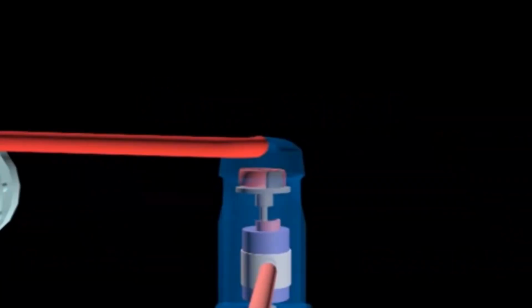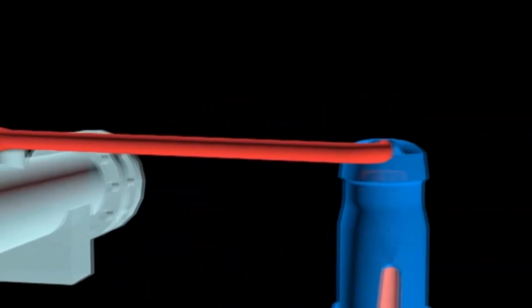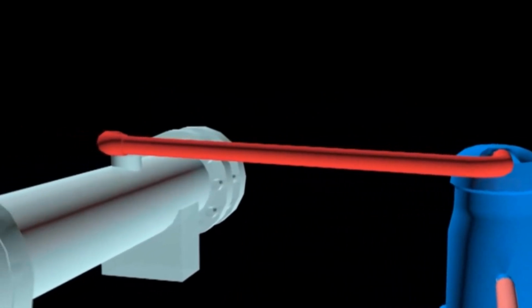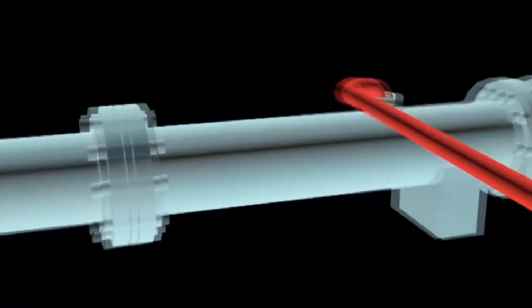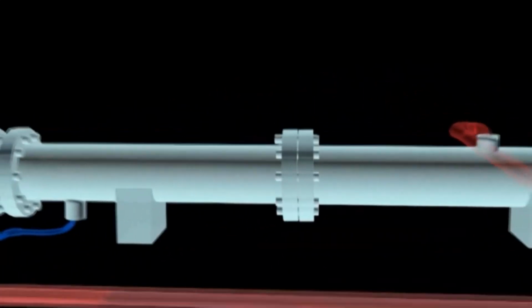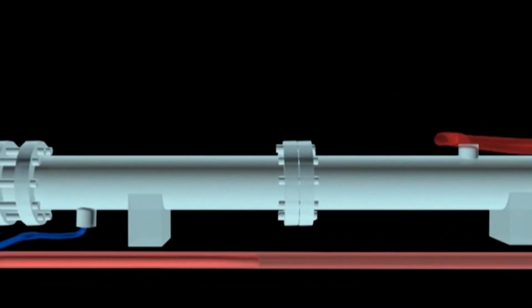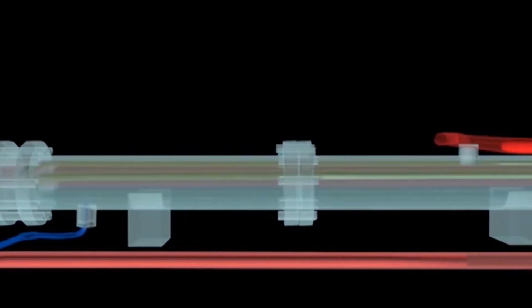Condenser. The refrigerant as a high pressure gas enters the condenser at a temperature higher than the temperature of the condenser water. In the condenser, the heat is eliminated to the condenser water from the cooling tower through convection and conduction. After the heat is removed, the refrigerant is condensed into a high-pressure liquid when it leaves the condenser. The most commonly used condenser is the shell and tube type. Water flows through the tube while refrigerant liquid floods the shell.